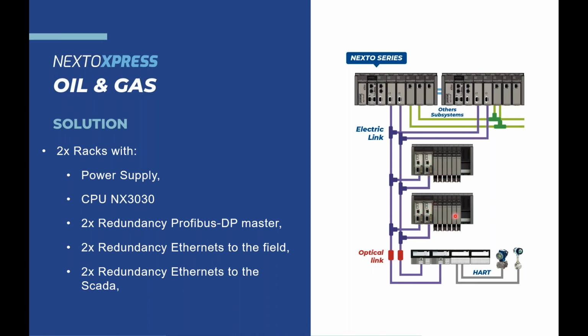And even if more modules fail, let's say that in this module, in the first half cluster, we have a second major fail. If this module fails, the system will switch all the control to the second half cluster that is just standing by, and we keep control of both networks, all the remotes, with all the information in the CPU synchronized with the first one. So the field itself from here down, no one knows what's going on over there, and that we have a major fail here in this module.